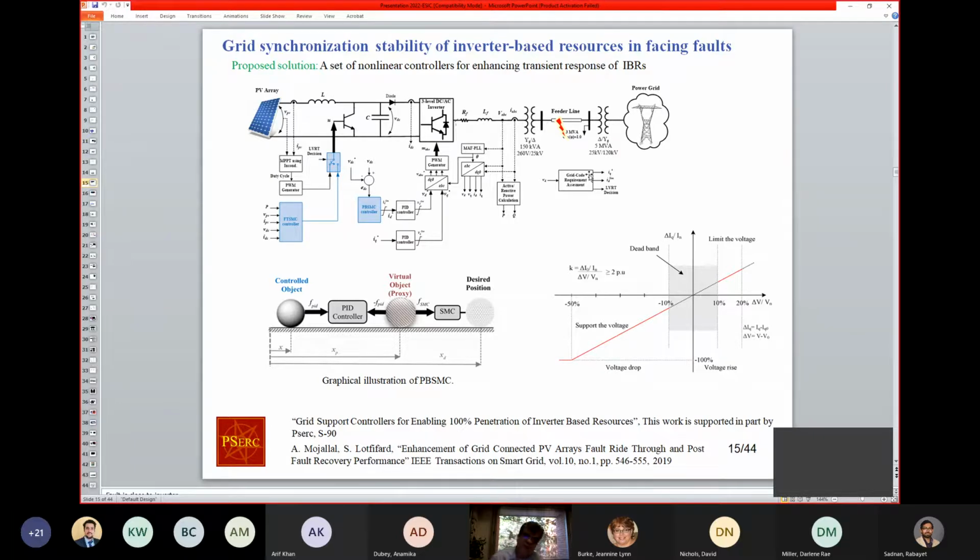Traditionally in the power grid, we usually use anti-windup. You can make anti-windup as complicated and complex as possible, but usually we don't use it for power systems because the implementation is a challenge. Those that are commonly used are tuned mainly based on heuristic approaches, and there are many reports that in certain conditions they don't operate as expected and so on and so forth.